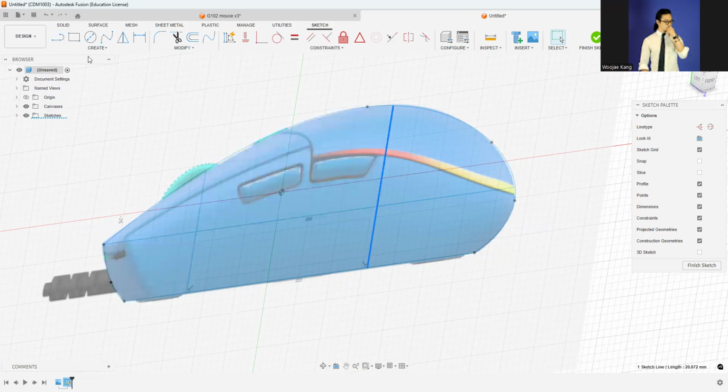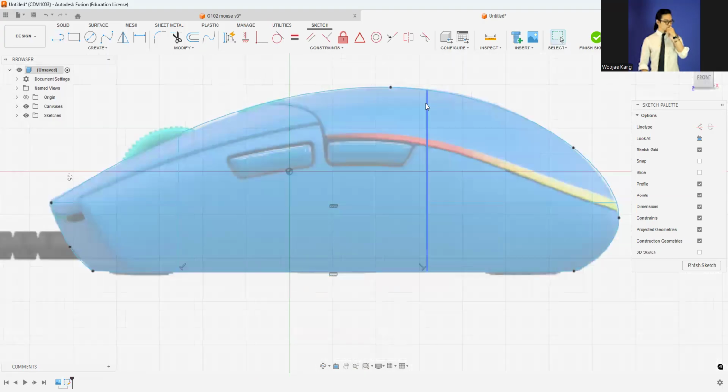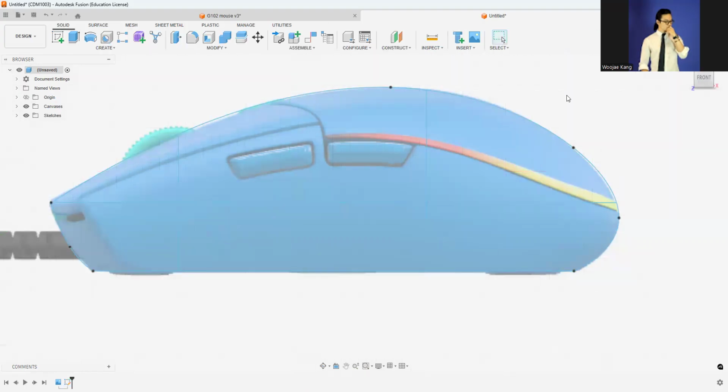The important thing is that when you draw the section lines here, you don't overshoot them when you go across the drawing. You must draw right to the end, because otherwise you can't use them as guide rails in the Fusion system. So make sure to draw this cross line not over it, but touching each end edge point of the drawing. That is really important.